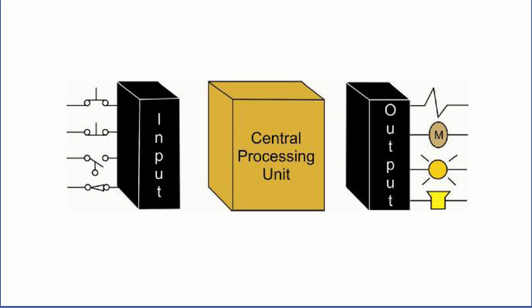So whenever no object is there, the PLC is getting a continuous signal, which is a digital signal. Digital signal means it is either 0 volt or 5 volt or 10 volt, according to the type of the sensor and the PLC that you are using. Now you see, this type of signal can either be on or off. That means this is a discrete signal, if you want to classify it in terms of the signals that we have seen already: one is the digital type, the other is the discrete type, and the third one is the analog type.